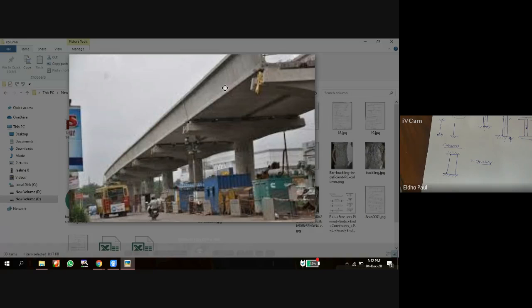A bridge? Yes, this area is a type of beam. What type of beam is it? What is the end condition of this beam? With an overhang, don't we need two end supports? Here we have only one support. What is the end condition with one support? Yes, it's a cantilever beam.